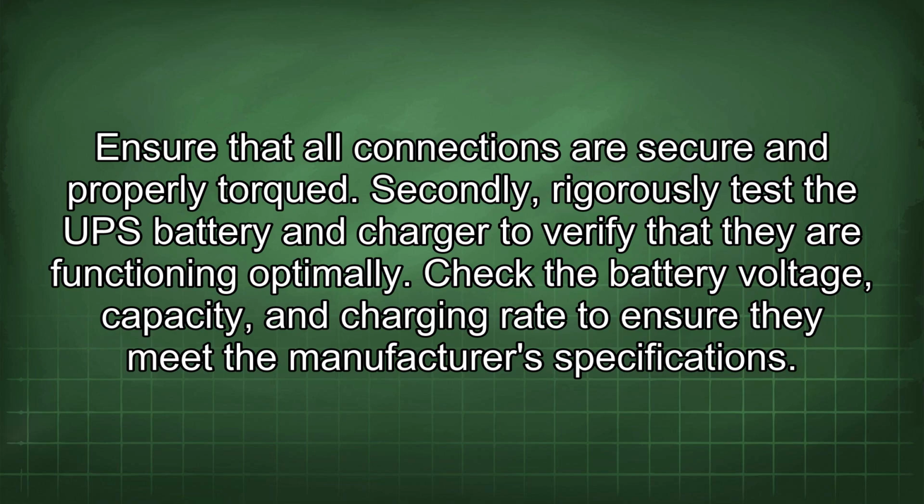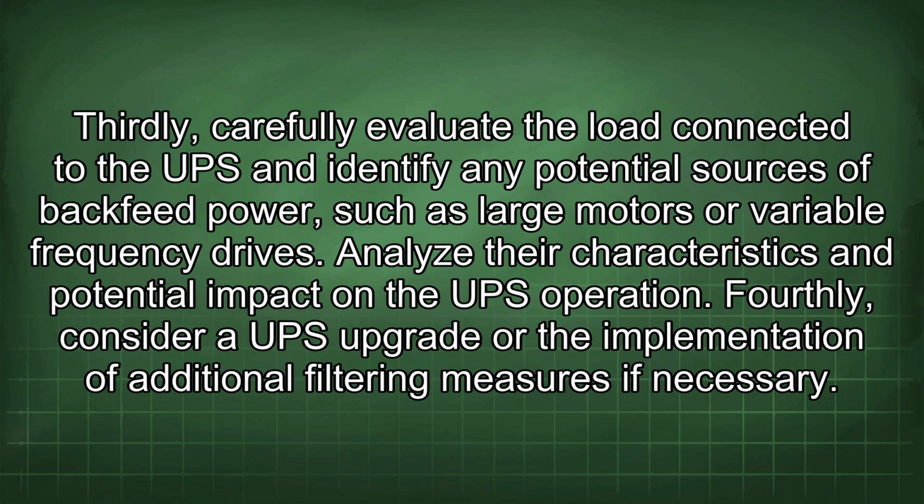Secondly, rigorously test the UPS battery and charger to verify that they are functioning optimally. Check the battery voltage, capacity, and charging rate to ensure they meet the manufacturer's specifications. Thirdly, carefully evaluate the load connected to the UPS and identify any potential sources of backfeed power, such as large motors or variable frequency drives. Analyze their characteristics and potential impact on the UPS operation.